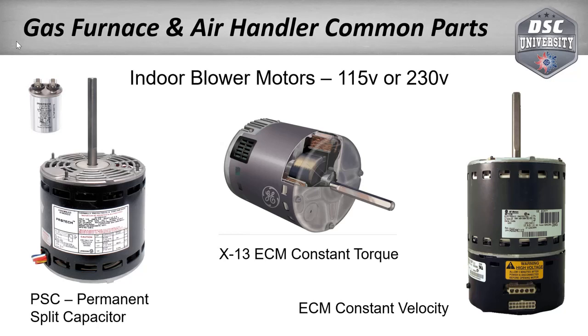Before then, all we had was PSC motors and then the higher dollar ECM motors. So they needed a motor that fit somewhere in between that would give you some better efficiency, but didn't cost as much as one of these. And so they developed that. It's an ECM motor, but it's basically a stripped down version of it. It doesn't have all the bells and whistles. So you get the efficiency of the top of the line motor, but it's closer to the price of your standard PSC motor. So it falls somewhere in the middle there.